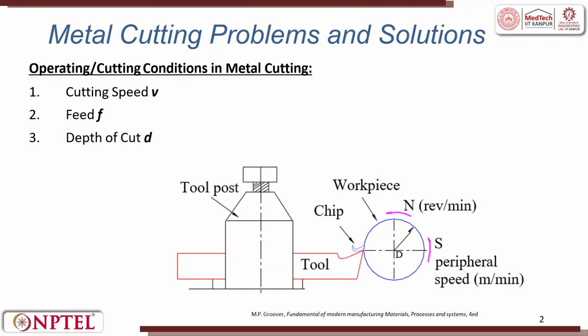Just to recall the concepts that we have discussed in the last week about the cutting speed, feed and depth of cut, because generally when we have specific dimensions of the material, we have a specific machine in which the machining speed is specifically defined. There are variable speeds in the CNC systems. For example, if the speed variation is between 0 to 10,000 rotations per minute, we can set even 9992, we can set even 8884, and the variation of 1 meter per minute speed could be put as an input there.